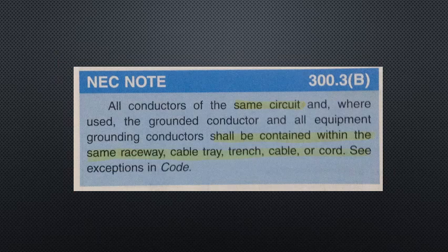Second, normally single conductors may only be installed as part of a wiring method recognized by the code. Thus, routing individual conductors without the protection or support of an approved wiring method is strictly prohibited. And third, for a circuit, the current carrying conductors, neutral conductor where used, and equipment grounding conductor must all be run within the same conduit, cable, duct, tray, or enclosure. Failure to comply with these requirements could lead to inductance problems.